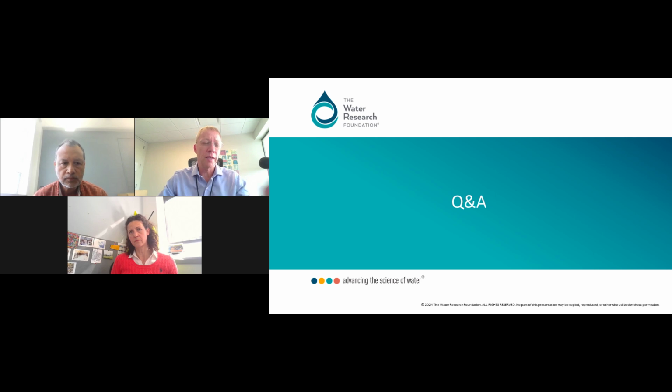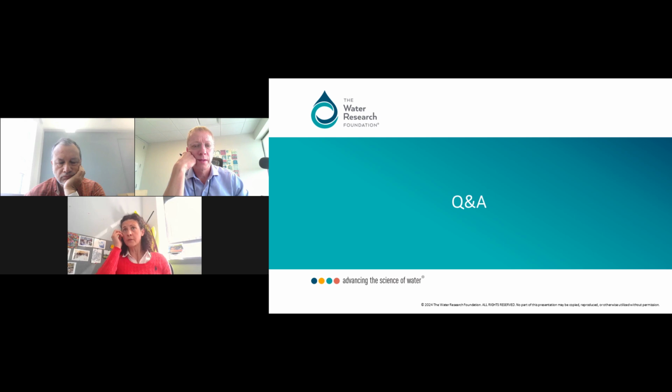Thank you. We've had a couple of questions come in related to HRT, including one: what is the range of HRT to be considered challenging for low DO operation? Yeah, Dan, please jump in. My experience is empirical from utilities that are operating like that. As I said, at Pomona, the aerobic HRT at the time of breakthrough of the high ammonia concentrations in the diurnal effluent was around 3.5 days.